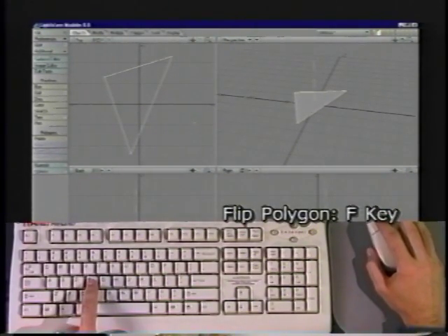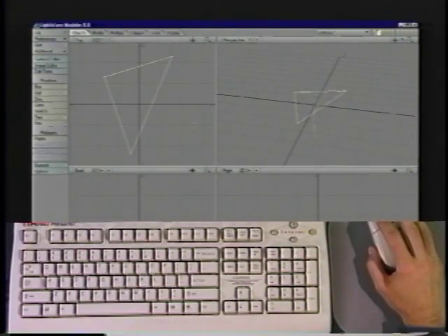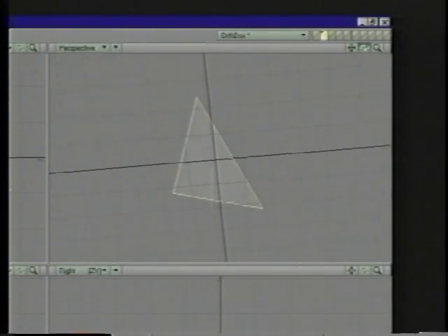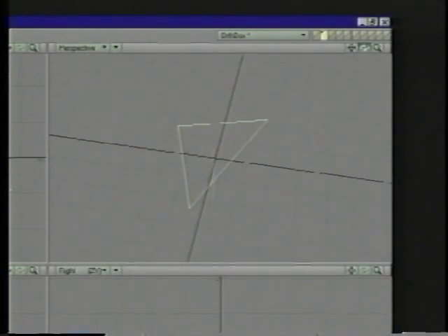And keep your eye on the perspective up here when I hit F. Boom. Okay, did our polygon disappear? No, it's just facing the other way now. And you'll see that the surface normal is now pointing exactly the opposite direction as it was before. Okay, so what if we want a polygon that is visible from both sides? Well, that's a very easy thing to do as well.